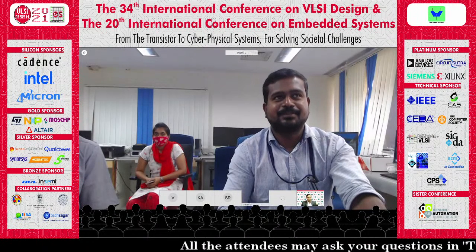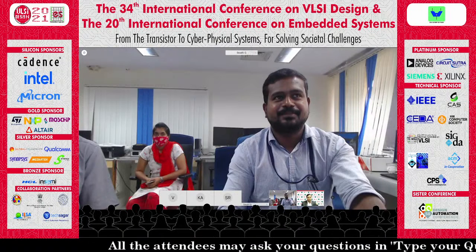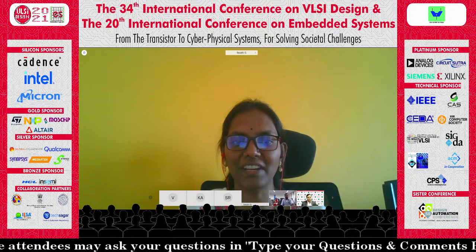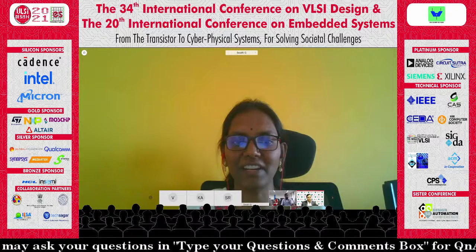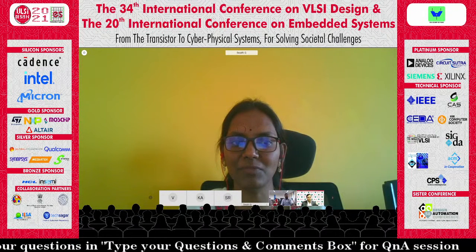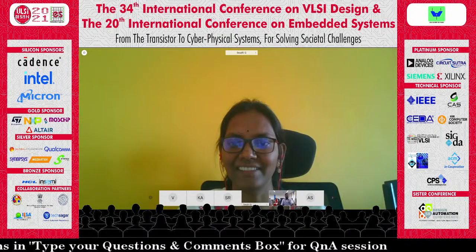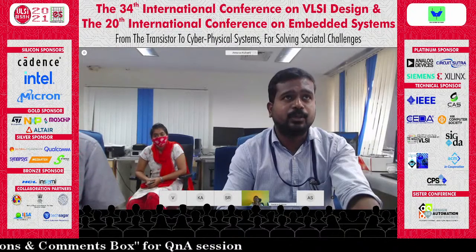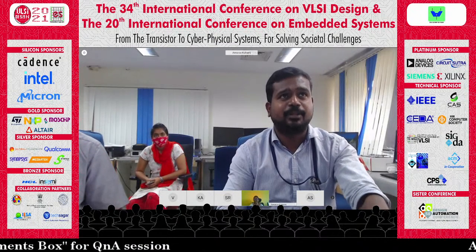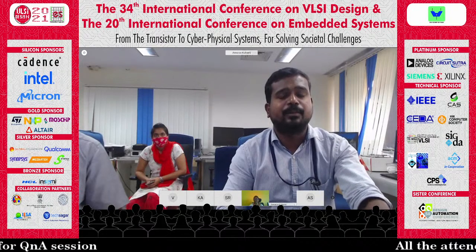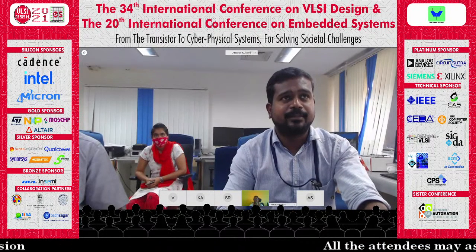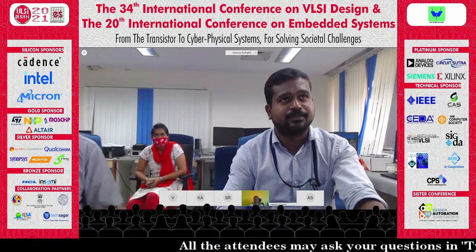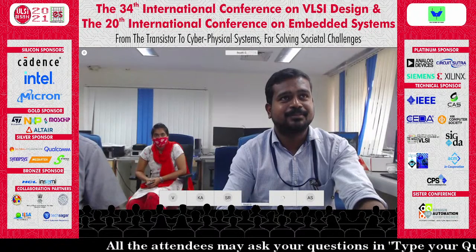Yeah, one question from my side. In the future work, you have mentioned extending this POSIT-Gen to cover all operations, right? I'm curious what percentage of operations are covered today with the existing POSIT-Gen. For this work, we have done fused multiply-accumulate, and division and square root are considered. But from our organizational perspective, we have currently done all the 64 operations of the RISC-V ISA compliant POSIT, and we have good results.